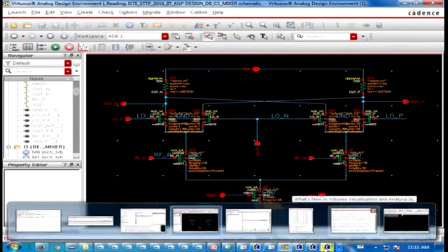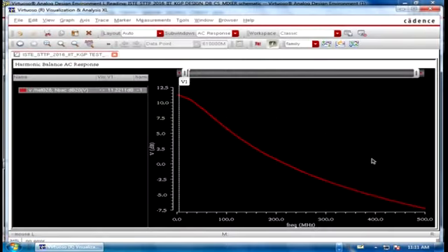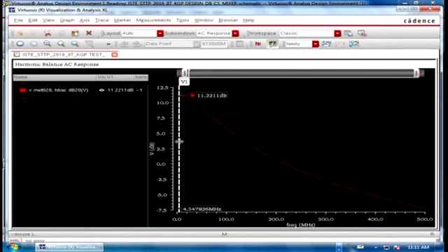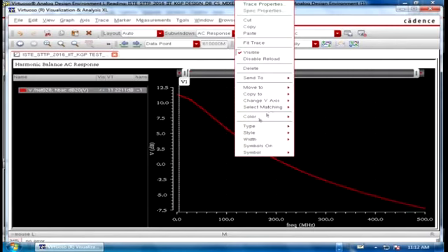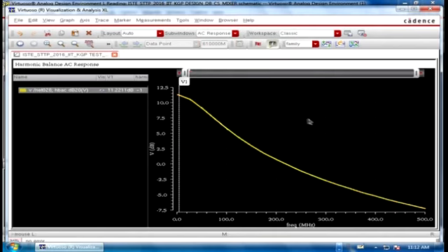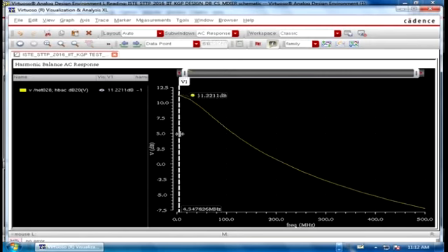First, let us look at this conversion gain. Because the IF band here is 2 megahertz, you go to the theoretical prediction and then go to the schematic. So this is frequency in megahertz, and that is the approximate conversion gain at 2 megahertz, approximately 11 dB.